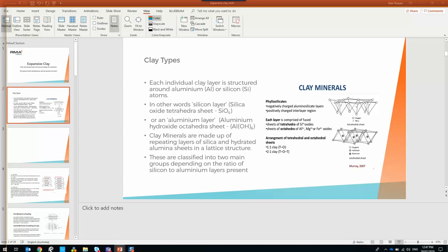So that works quite well if you have to build a site up to get it out of the flood levels. And they're the sort of design options you get. But rule of thumb, you need at least 1.5 metres to make a difference. 1 metre's still not quite enough for me to be comfortable.